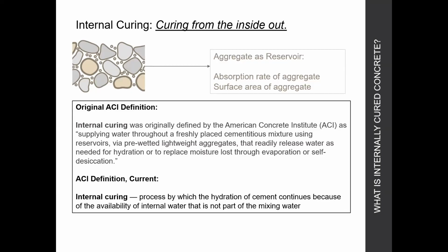So when you soak it and it comes into the mix carrying water, it brings water as a gift to the mix, and it's mixed in evenly, and that aggregate is the source of the internal curing. But that definition changed and opened up a little. This didn't just happen this year, so I'm just getting you up to speed. The new definition doesn't rely on the aggregate as the reservoir. The aggregate doesn't have to be the one to bring the water to the mix. It can still bring water depending on how absorptive it is, but it's no longer necessarily locked into the definition.